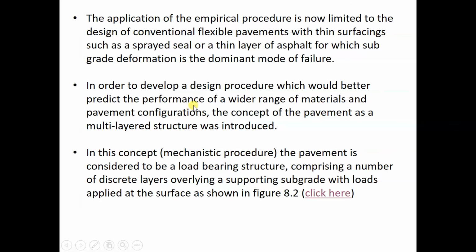The application of the empirical procedure is now limited to the design of conventional flexible pavement with thin surfacing such as spray seal or a thin layer of asphalt, for which the subgrade deformation is the dominant mode of failure.